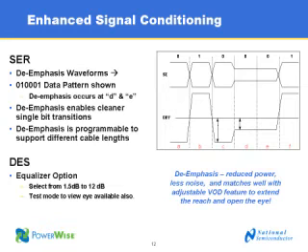Okay, moving on to the next thing, I'm talking a little bit about the interconnect and how we've enhanced the signal conditioning to allow us to drive the long distances with the higher data rates. So at the serializer, we've added a de-emphasis feature. Now what we're showing here on the right is an example of how de-emphasis works. And so we have a series of transitions starting with the pattern going from a 0 to a 1, then to 3 zeros, and finally another 1.